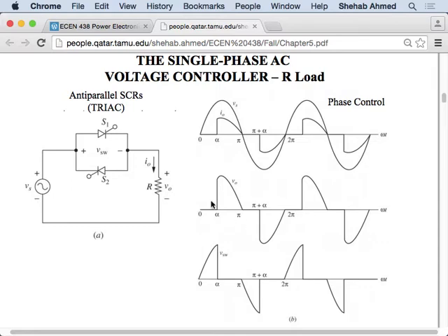And then I have these huge jumps, right? These huge jumps indicate a spectrum of other components, lots of other components as well, right? But are they significant compared to the 50, 60 hertz component? No, the area under the curve for the waveform that's occurring at 50, 60 hertz is considerably larger. It will have significantly more effect. There will be much more power in that spectrum by just looking at the waveform, right?